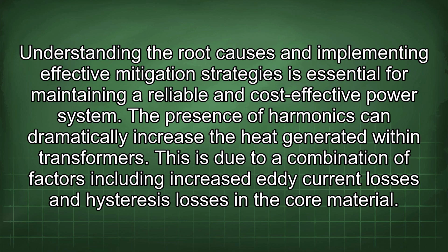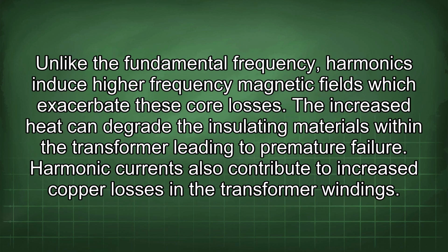This is due to a combination of factors including increased eddy current losses and hysteresis losses in the core material. Unlike the fundamental frequency, harmonics induce higher frequency magnetic fields which exacerbate these core losses. The increased heat can degrade the insulating materials within the transformer, leading to premature failure.